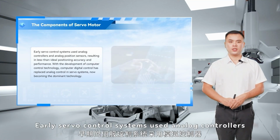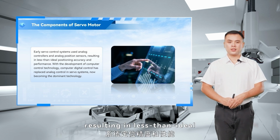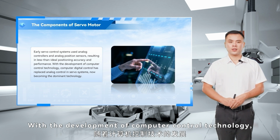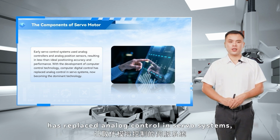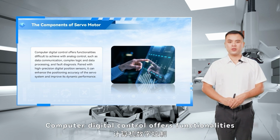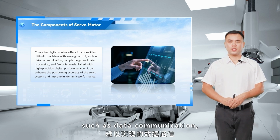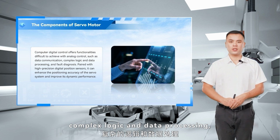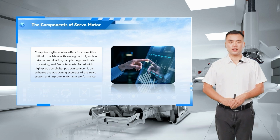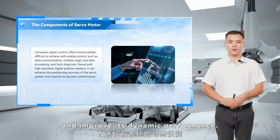Early servo control systems used analog controllers and analog position sensors, resulting in less than ideal positioning accuracy and performance. With the development of computer control technology, computer digital control has replaced analog control in servo systems, now becoming the dominant technology. Computer digital control offers functionalities difficult to achieve with analog control, such as data communication, complex logic, data processing, and fault diagnosis. Paired with high-precision digital position sensors, it can enhance the positioning accuracy of the servo system and improve its dynamic performance.